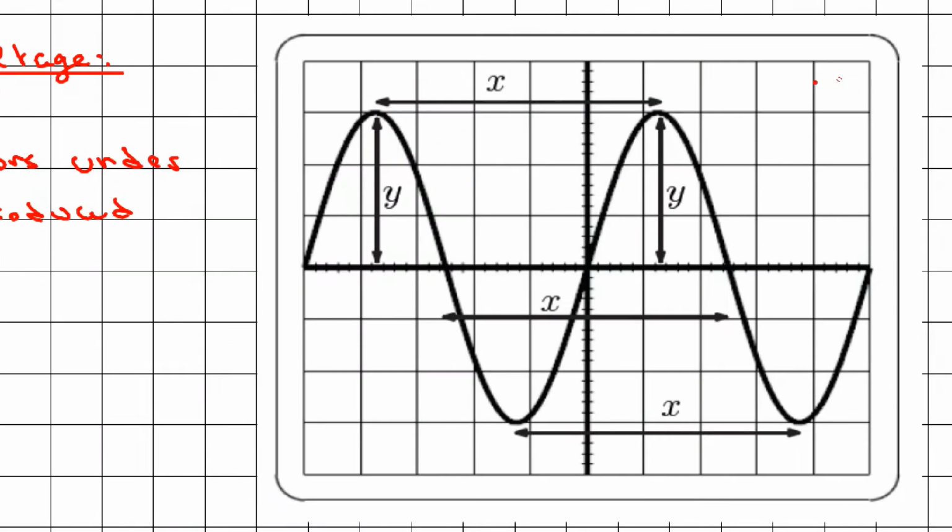So if you consider this point and we need to count the number of divisions X, we need to find another point in which the value of the voltage U is exactly the same, which is this point. X represents the number of divisions between this point and this point. If we count them, we have 1, 2, 3, 4. This one with this one will give us 5. So in this case, X is equal to 5 divisions.